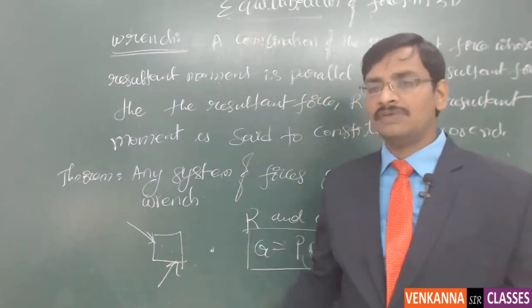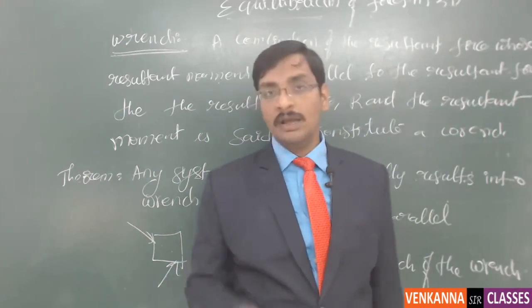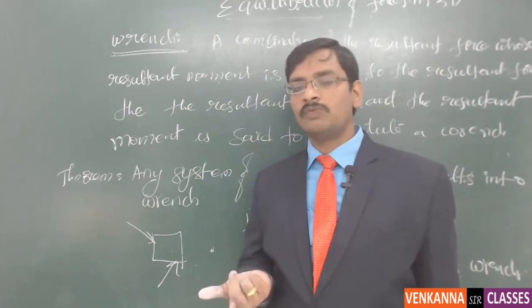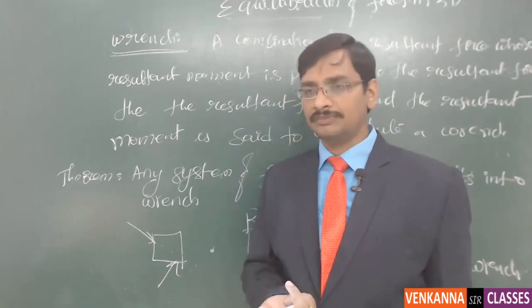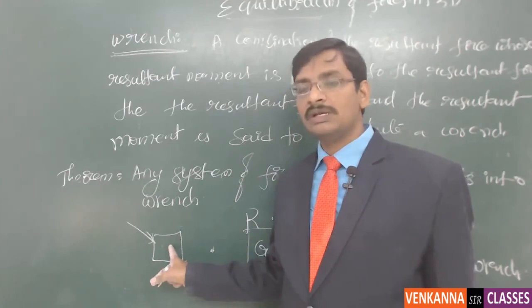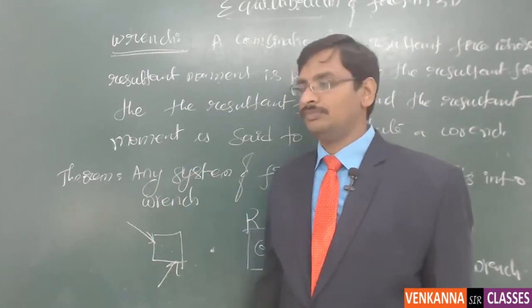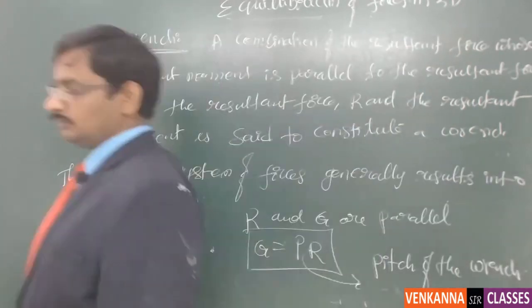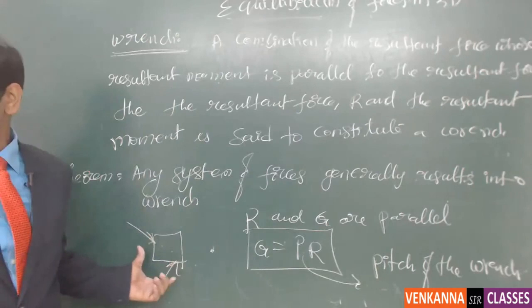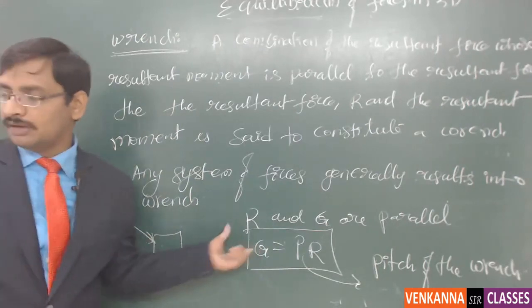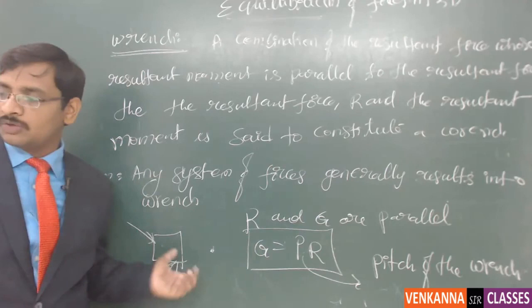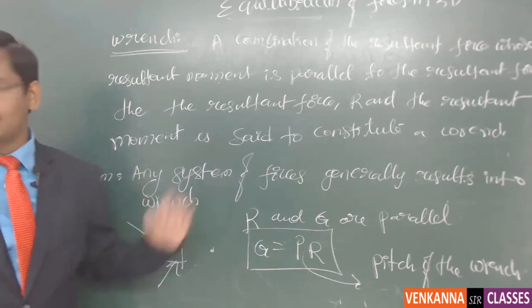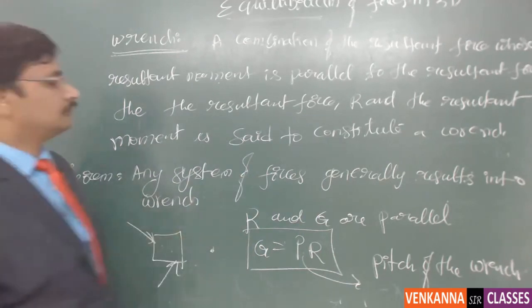The forces show no change whether coplanar or non-coplanar. But coming to G, which is the moment, in case of non-coplanar forces the direction can change in any direction. In case of coplanar forces, the direction of the resultant moment is always the same, irrespective of the base point. Got it? Because these are coplanar forces, these directions don't change irrespective of the base point. The moment is always perpendicular to the plane, so that also won't change. So this is applicable only for non-coplanar forces. You can specify that.